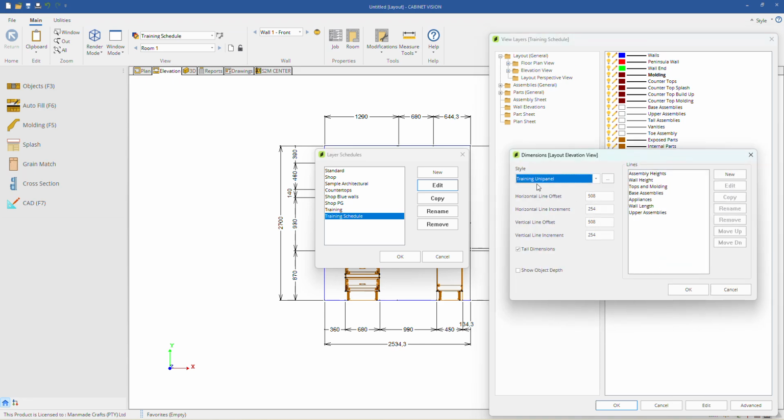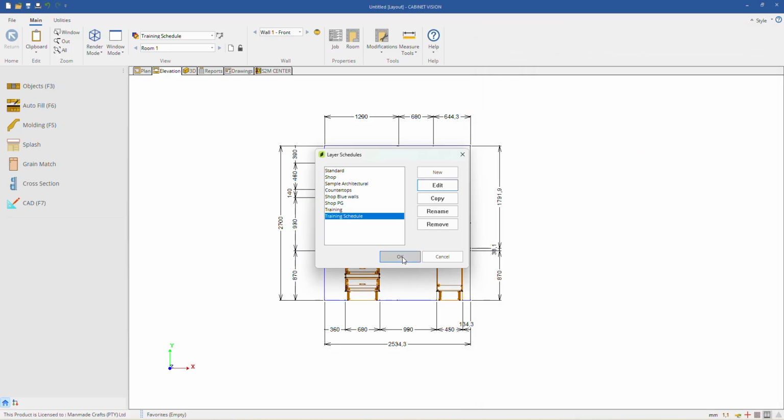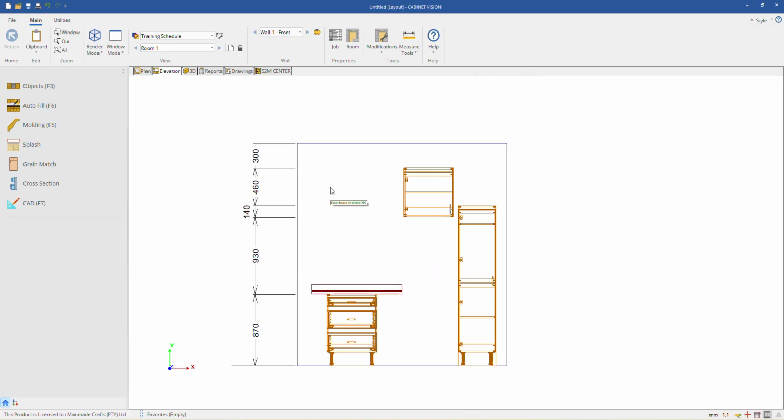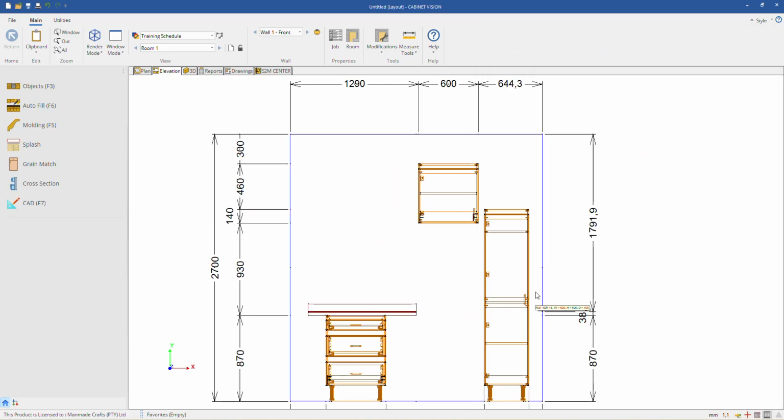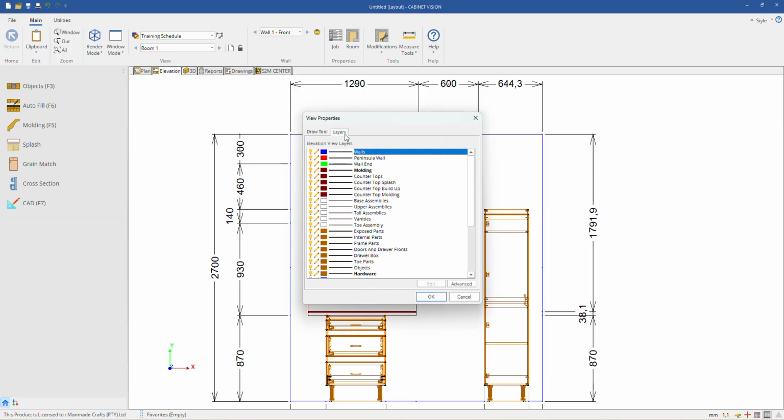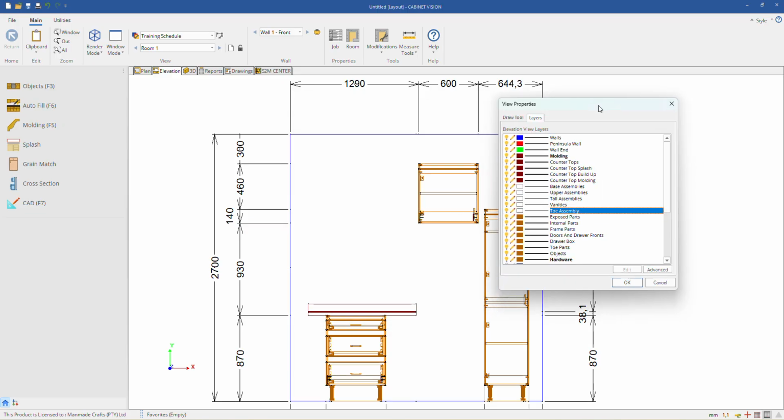Yeah. So if I go there now, it's already saved. Good. Nice. So you can modify this as you go through, or you realize, okay, but on my elevation view, I want to see these cabinets in different colors. So right click, properties, layers. I can go in here, but now you'll see, aha, I can't change it because it shows me all of my information in the units.